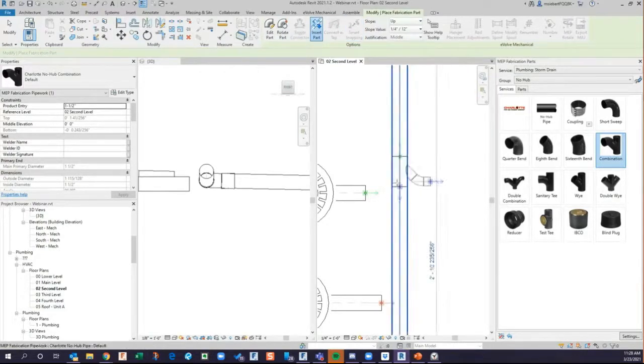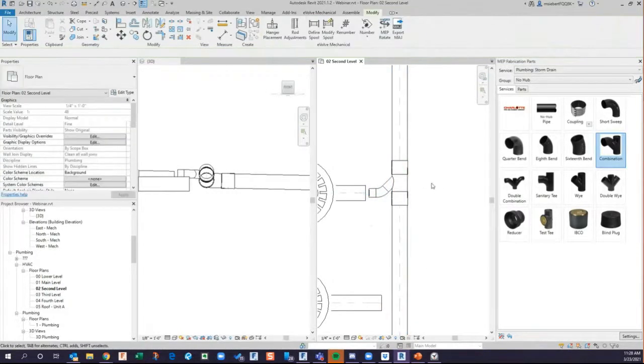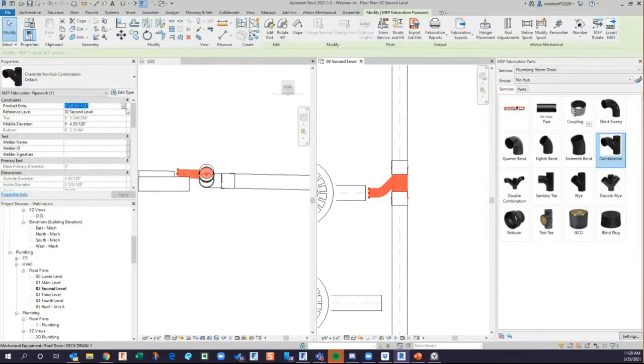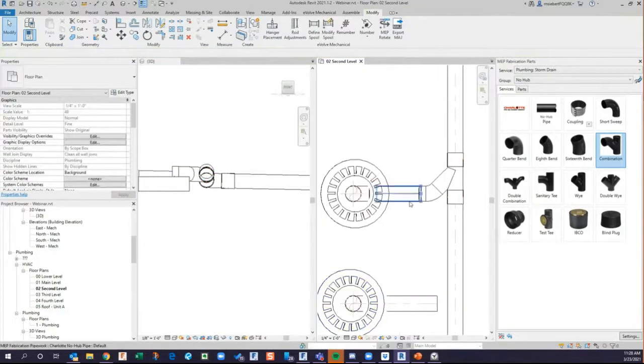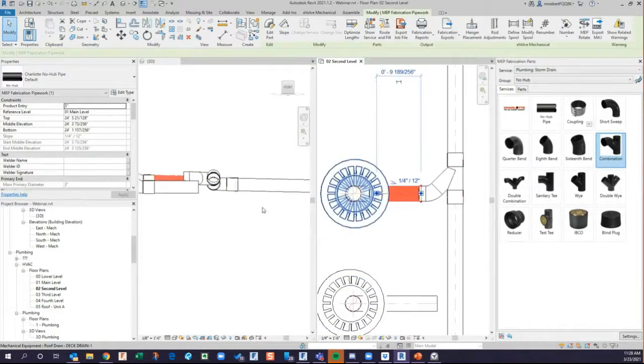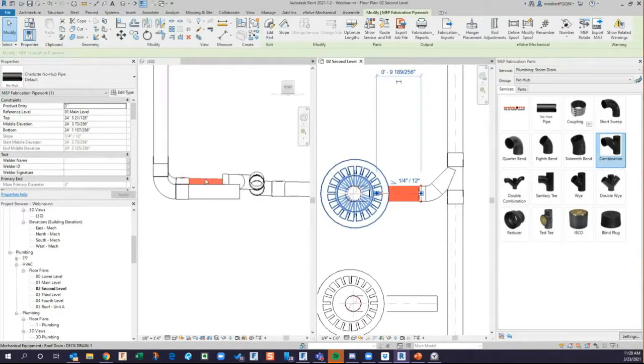Insert the part. And this is why I love doing a live webinar. So right there, I'm going to line this up, left click on it. It inserts it, but I meant to change that to a 3x3. Just like that. Apply. Now, notice that that's still too low. Okay, so I'm going to have to even bring that up higher.